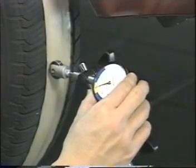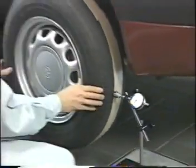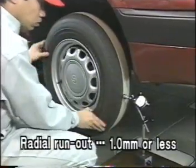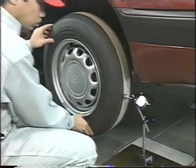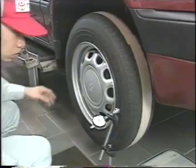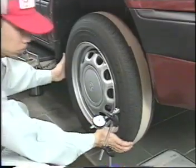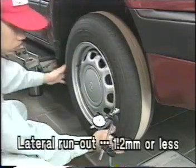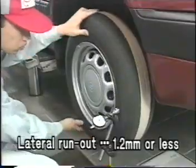Touch the spindle of a dial indicator to the center of the tire tread at a right angle. Turn the tire slowly by hand and measure the radial runout. Then touch the spindle of a dial gauge at a right angle to a portion of the side wall of the tire which has no protrusions or indentations. Turn the tire slowly by hand and measure the lateral runout.